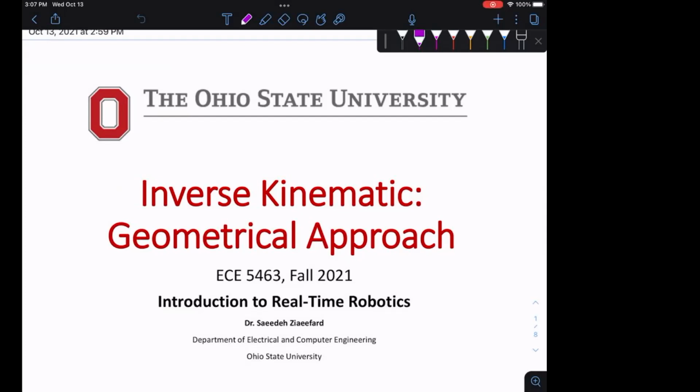Now the problem of inverse kinematics is, we have the same robot, we know the forward kinematic model, we already modeled it. Let's say the PA2, you modeled the kinematics of your system. Now, I tell you this end effector has to reach this point. You know X, Y, Z, and orientation of this point, so you know all 6 elements. How do we change the joints?